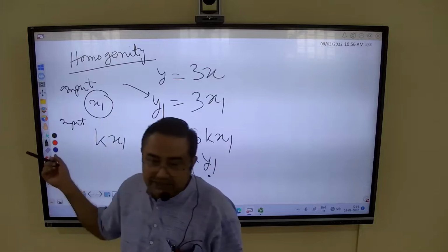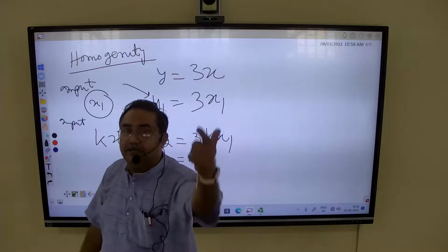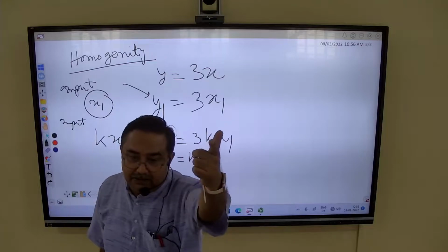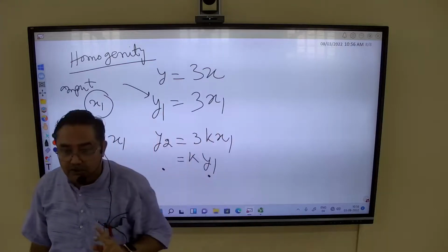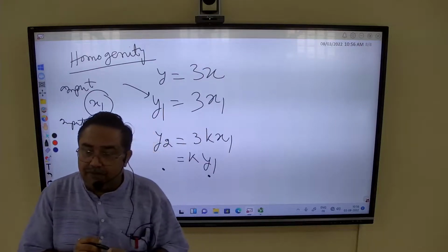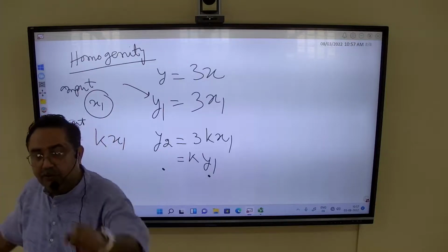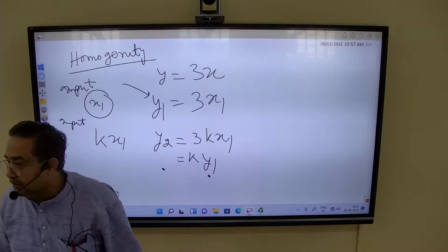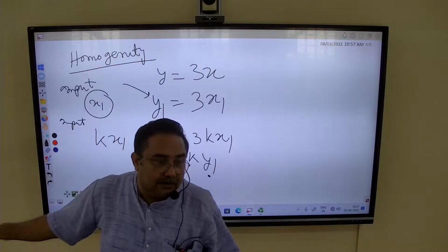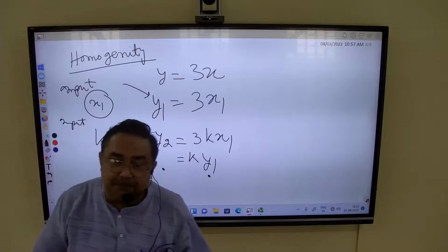So measure these two quantities: apply 50 volt, measure the speed, apply 100 volt, measure the speed. Is it clear? And now you can verify also. You have taken two readings. So first of all, additivity principle, how? 50 plus 100, 150 volt. Okay, you apply 150 volt, measure the speed. Now after application of 150 volt, is the speed equal to the sum of the speeds at 50 and 100 volt or not? If it is there, it is obeying the principle of additivity.